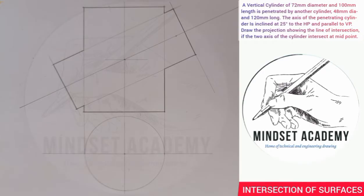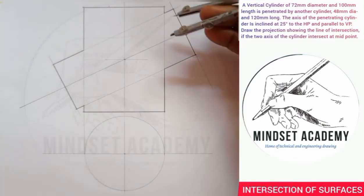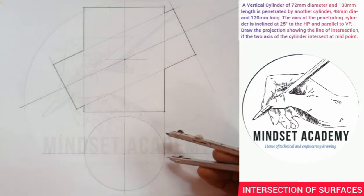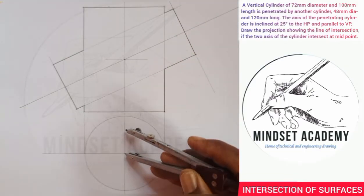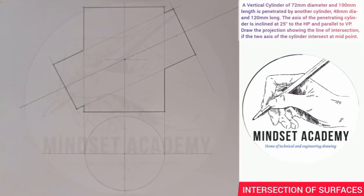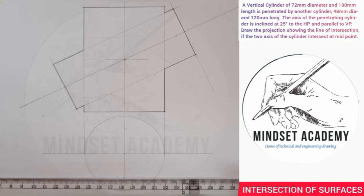Now in doing that, we'll draw it on the what? On the plan also, because this is the same diagram here. So if I take the same measurement here, we know that from this point to this point is 24, right? And I'll place it at this point. I'll mark 24 up, 24 down. Then I'm going to project those 2 points this way.